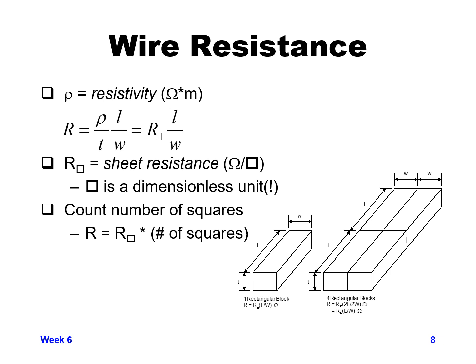So our sheet resistance is in ohms per square, and then we need to count the number of squares to determine the total resistance of that wire. And the number of squares is the length of your metal wire divided by the width. So that's the definition of the total number of squares of your wire. So a given wire that is a length of L and a width of W will be the same number of squares as a wire that's twice the length and twice the width of that wire.